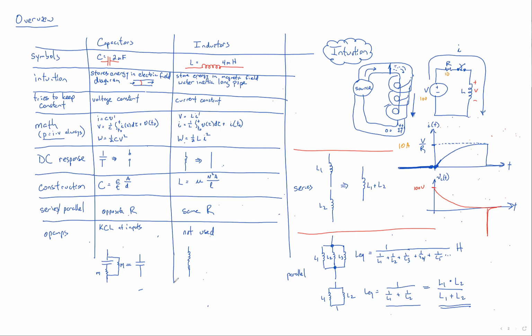Secondly, a real inductor creates a magnetic field around it. And this magnetic field extends out of it quite a bit. Looks like that, if you could visualize it in 3D, like a donut going right around it. If you have 2 inductors that are close to each other, those magnetic fields interfere with each other, and they end up becoming a transformer, and then they don't behave ideally at all. So in general, we try not to use inductors if we can.